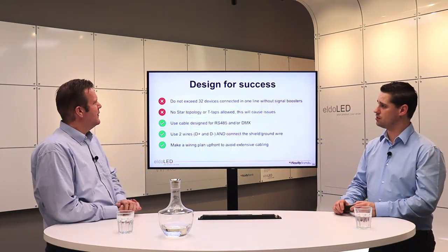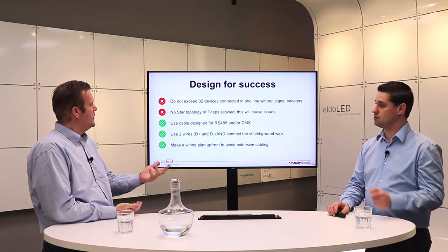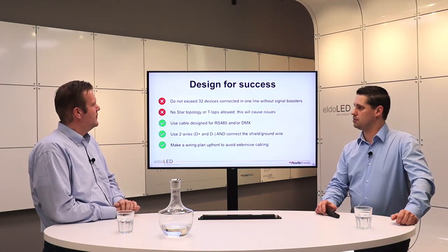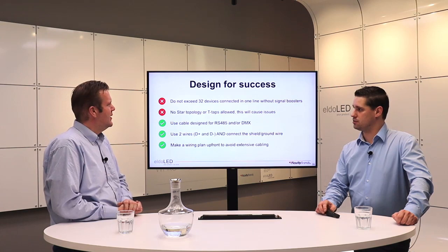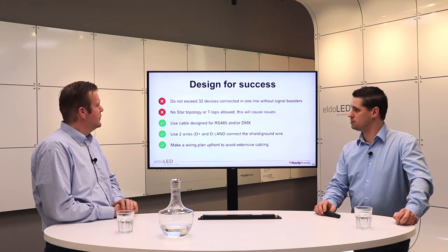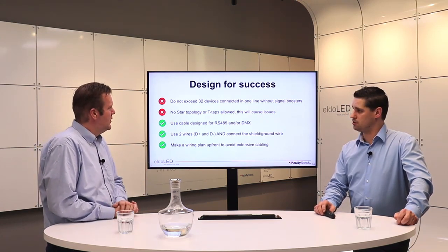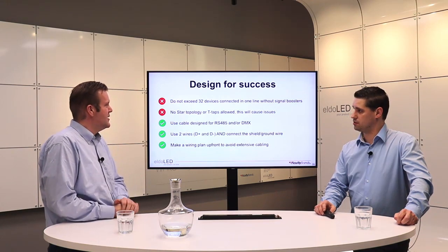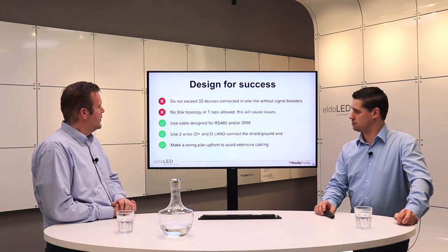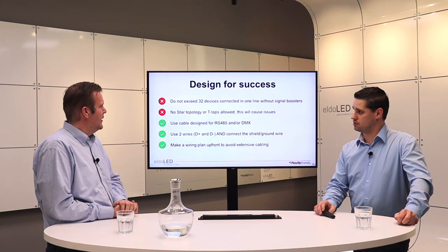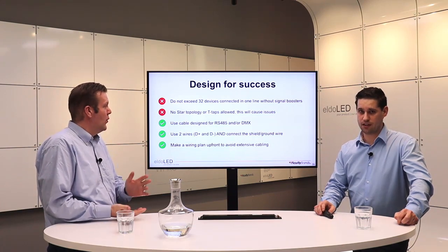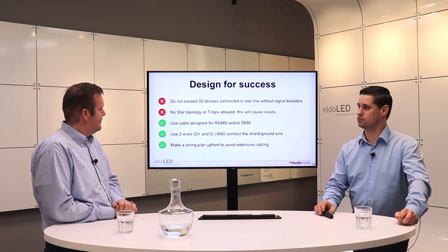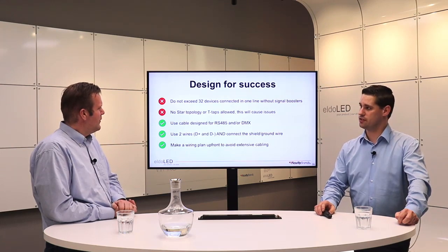So other stuff on Design for Success. What you don't need to do is put more than 32 devices in a line without a signal booster, no star topology, no T-taps allowed. This will cause issues in the end. And the most important one is to use the correct cable designed for RS485 and/or DMX. True. Absolutely. And true. Wiring?